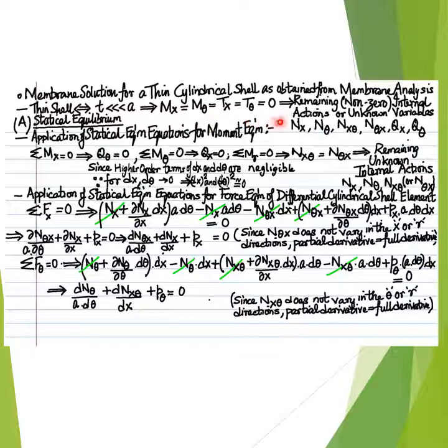And also noting that the flexural rigidity or the bending stiffness of a thin cylindrical shell that satisfies the necessary and sufficient condition to qualify as a thin shell in case of a cylindrical shell structure, as expressed by this inequality, is negligible, the outer plane bending moments mx, m theta, and the outer plane torsional moments tx, t theta have to vanish, since the thin cylindrical shell is unable to resist any outer plane moments.